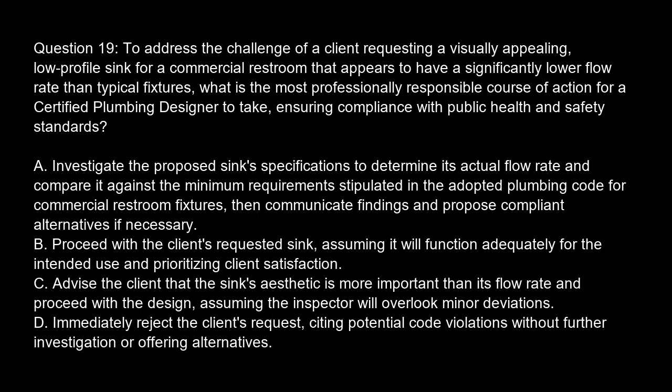Question 19. To address the challenge of a client requesting a visually appealing, low-profile sink for a commercial restroom that appears to have a significantly lower flow rate than typical fixtures, what is the most professionally responsible course of action for a certified plumbing designer to take, ensuring compliance with public health and safety standards? Option A. Investigate the proposed sink specifications to determine its actual flow rate and compare it against the minimum requirements stipulated in the adopted plumbing code for commercial restroom fixtures. Then communicate findings and propose compliant alternatives if necessary.